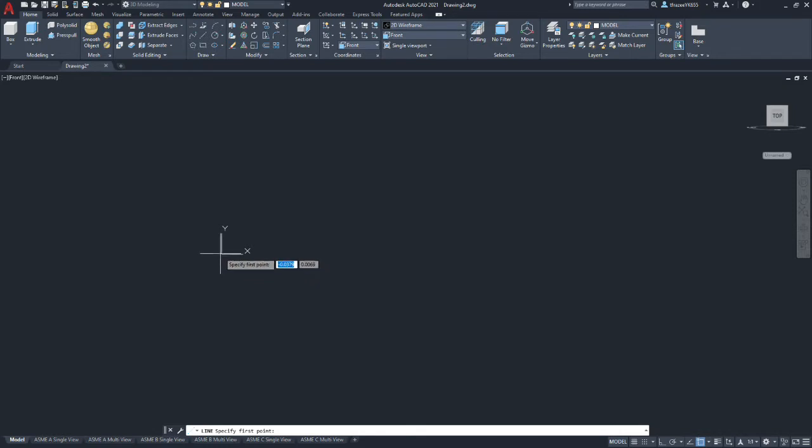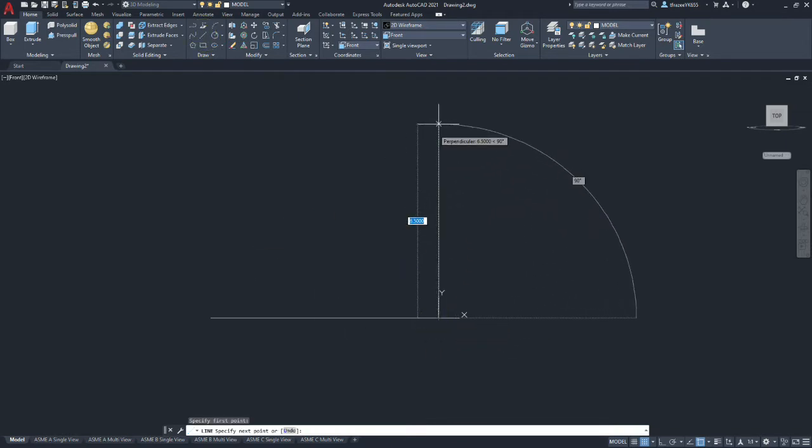We're going to place the origin, the corner of the part where the 9.2 dimension radiates from, as our starting point. So we go from origin, and we want ortho on. Draw a line to the left, and we're going to then draw a vertical line. Okay, I'm going to turn the grid snap off at this point, now that we have those two lines established.